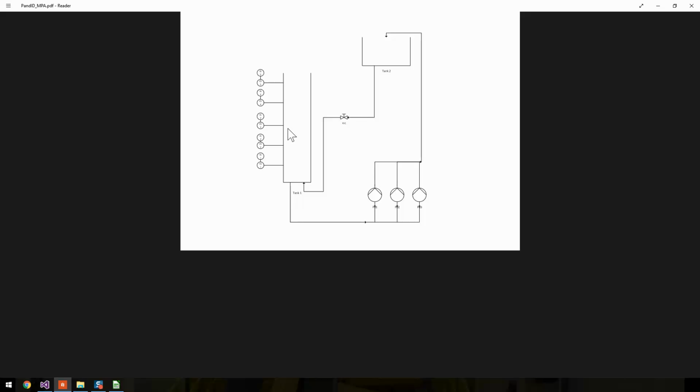We initialized it with a low water level, 31.8%, so it will never reach above these 2 sensors here because those are declared as 40% and 50%.